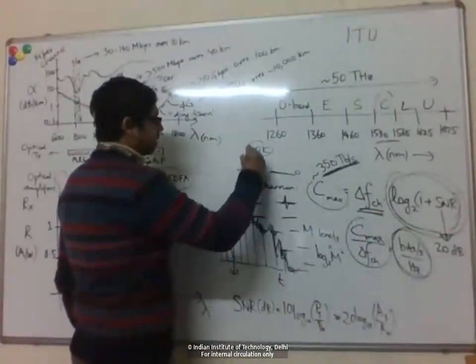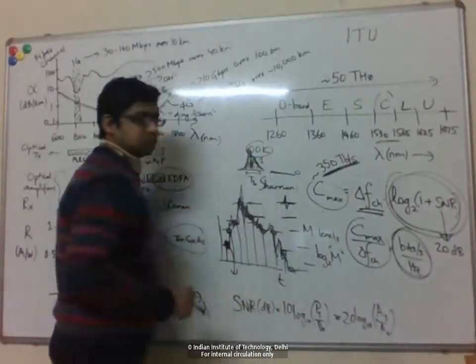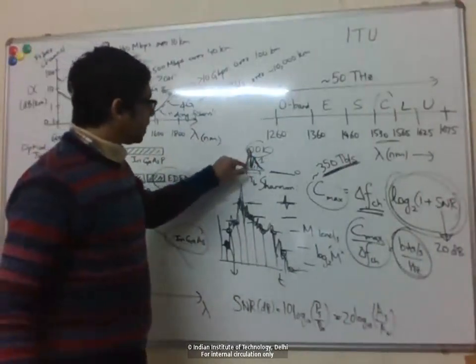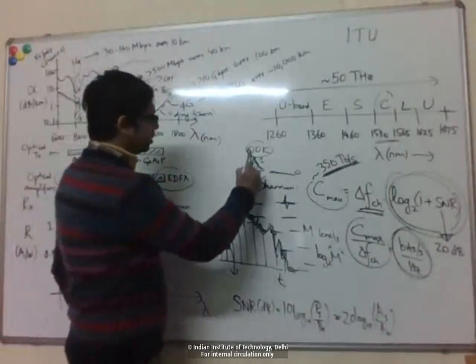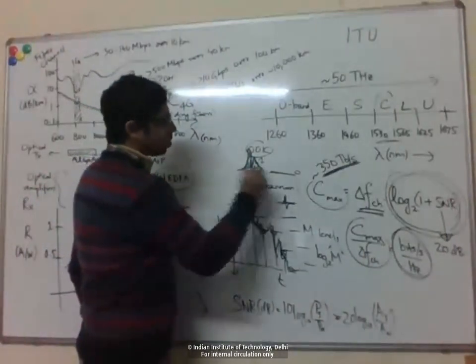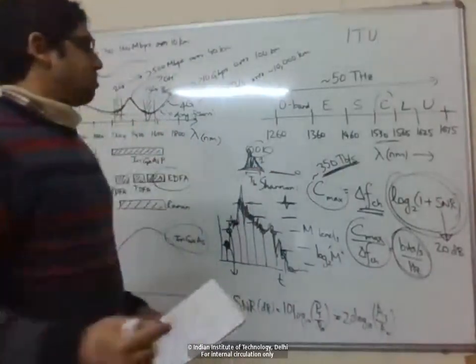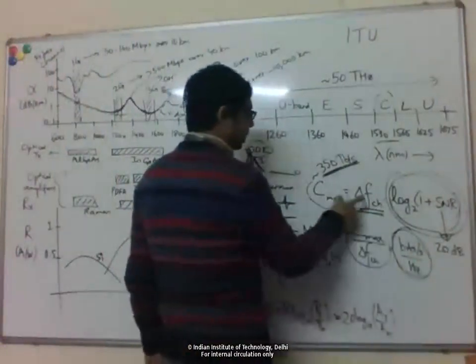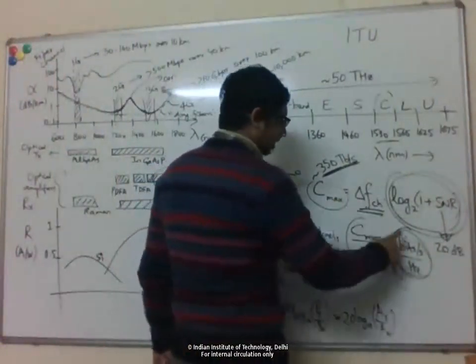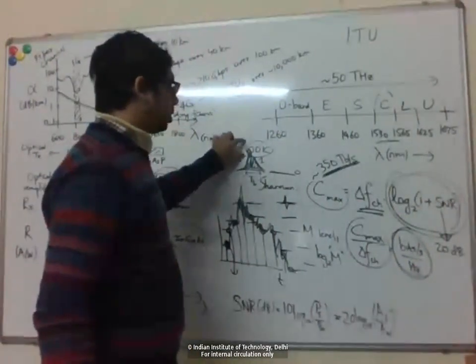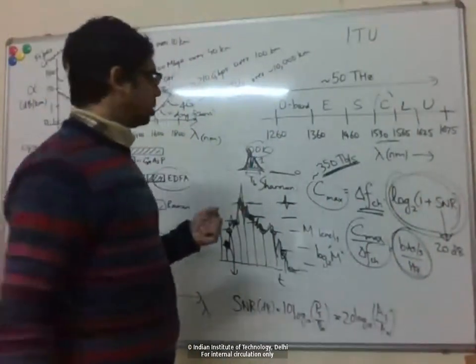For 1, I'm sending something. So if the maximum noise is less than the signal amplitude, such that with the noise this remains above 0, then I can still distinguish bit 1 from bit 0. So if you put SNR equal to 1 here, you get this is equal to this, or this is 1. So that's what the simplest on-off keying modulation scheme utilizes.